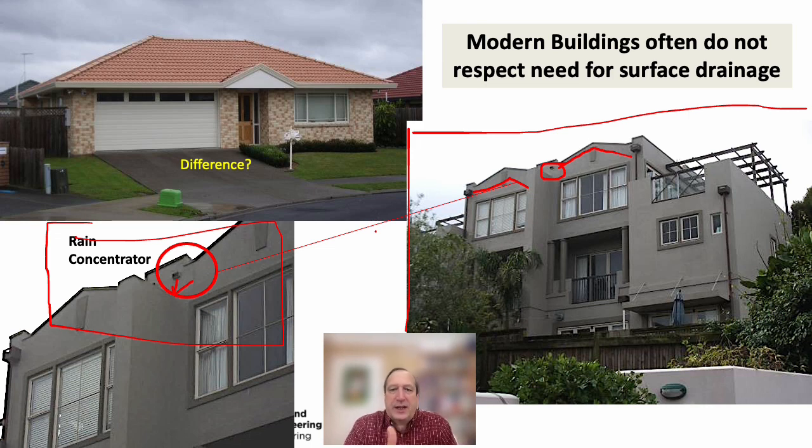That projecting wall is basically a flat top. It's dumping all the rain from this roof area, however deep the building is, on top of it. Any water that gets in will not have the benefit of accelerated drying by heat loss from the indoors, because it's outdoors on 3 sides.